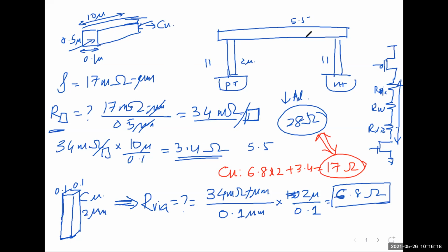High K is, like I said, in analog circuits, for example, you're doing an audio amplifier, right? You need an audio filter. The filters are in kilohertz range. Let's say your resistances are 1 kilo ohm, then your capacitance needed is in pico to nanofarad. But if you have a low K dielectric, then the area needed is high, right?